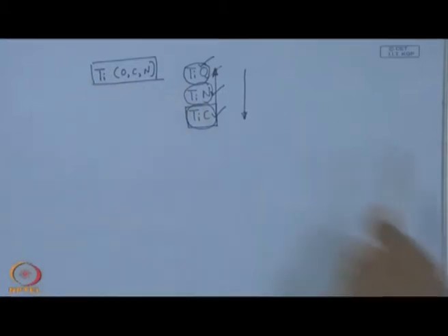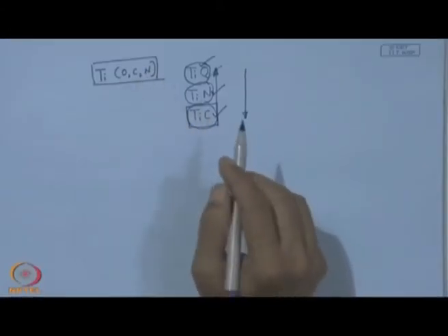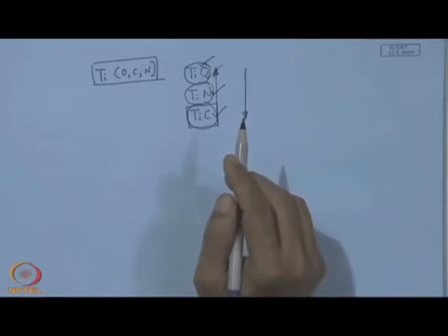However, it has to be also understood in clear terms that chemical stability alone cannot serve the requirement of the cutting tool. It is also abrasion wear resistance or hardness that is desired in the cutting tool. So, we can keep both the extremities together in right proportion, and we have titanium nitride in between, and putting this oxygen, carbon and nitrogen in right proportion, we can get a titanium oxycarbonitride.